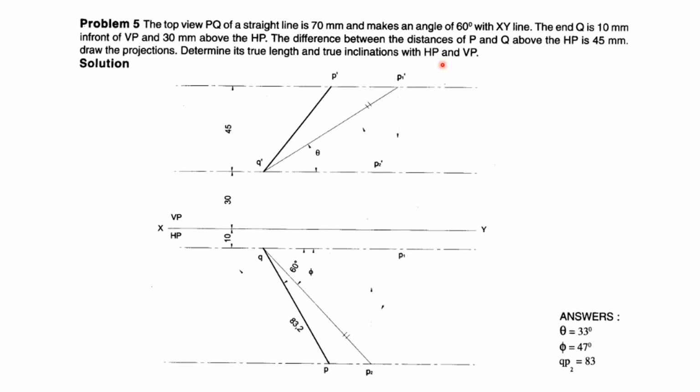First we will draw the top view, that is 70 mm with 60 length. Then we already have the locus line which they have given. So you can take an arc and a straight line, it intersects with the locus line of B, and from there you will get the true length. Like this, we have three categories or varieties of problems in the projection of lines.